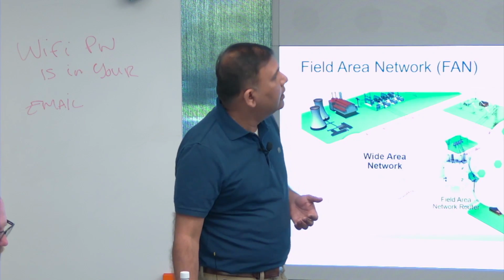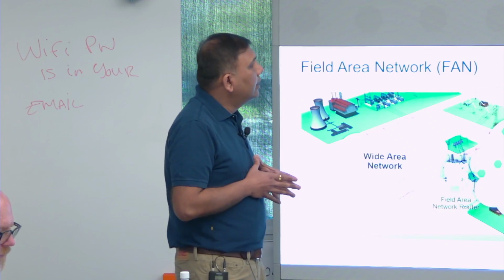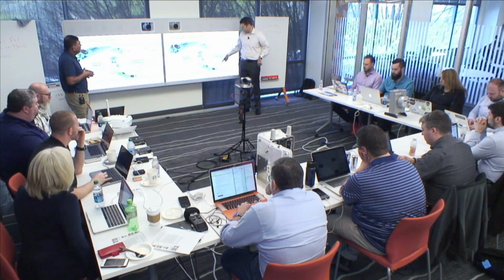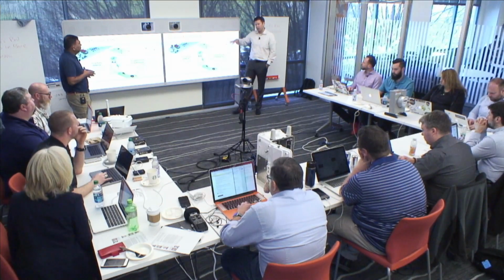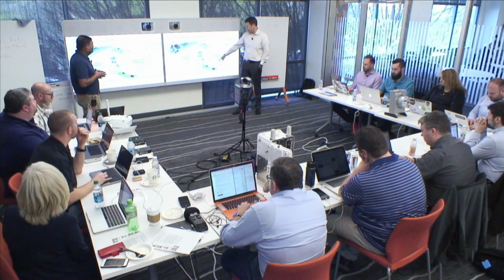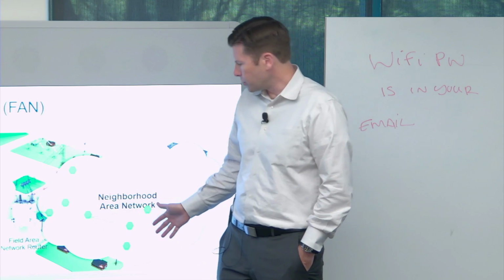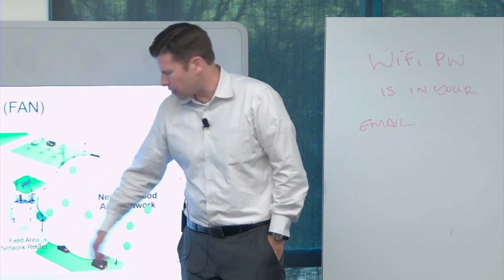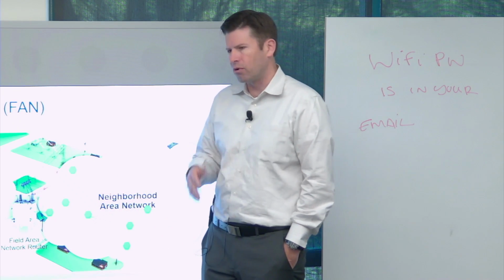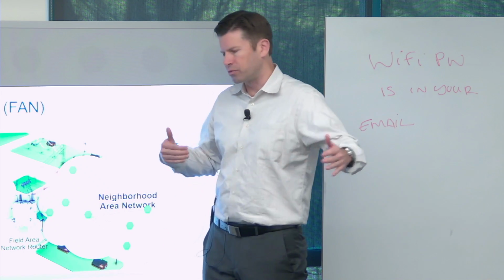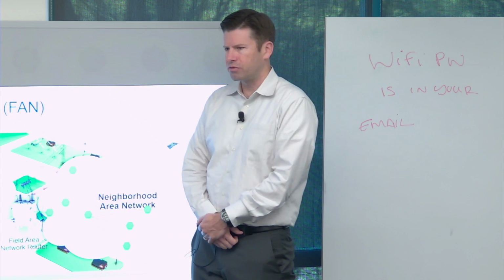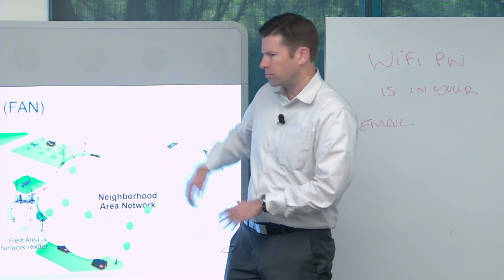Yep. And so in the mesh network, all the sensors, like we were saying, both generate and repeat the signals from other mesh nodes. We'll explain how the mesh forms and operates and how we form the best path of the network. Okay, cool. In our typical environments for smart metering, most meters will get to the router in 2 to 4 hops. But in rural environments, we've seen it go up to 20 to 25 hops. There's really no limit in terms of how the mesh can scale up.